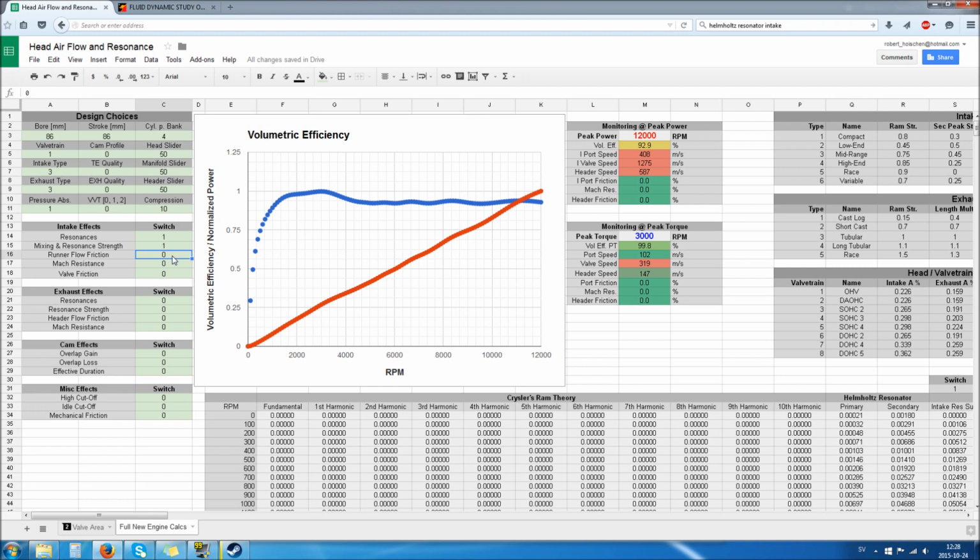Because let's say you have a tiny pipe, but that tiny pipe is very short. If you apply enough pressure to it, you can still put through a lot of air there. But if you make it longer, it becomes harder and harder. And that is modeled with this effect, which limits airflow in the high end. I can switch it off again, and we can make sure that it doesn't breathe as well.